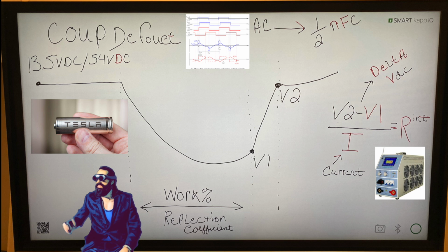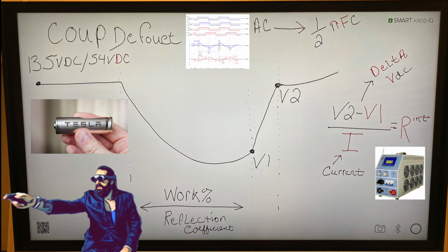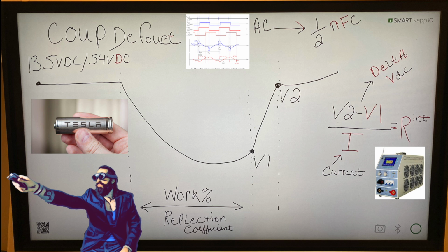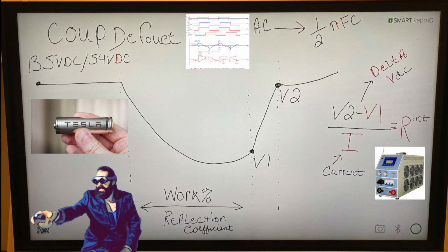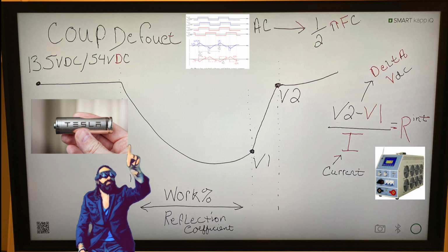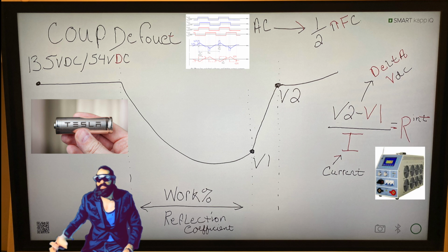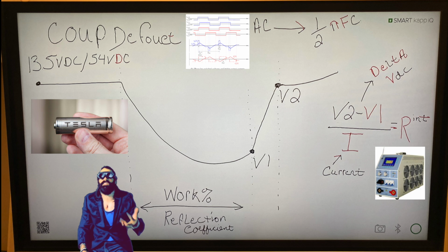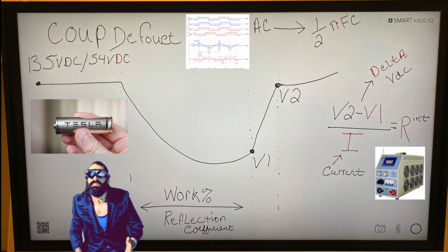And what we generally do is this resistance here that we're inducing from the DC load bank, if we're doing 54 volt load steps, generally in a 540 volt DC bus, you would have 10 load steps at 54, and then this load bank would probably be about 1.6 ohms, right? So if you use Ohm's law, very simple again, you got 54 volts divided by 1.6, what are you getting? You should have about 30 amps. And that's pretty amazing. It's simple stuff that you can look at, you can implement, you can show, you can discuss and review. And again, as you're looking at these systems and battery technologies, if you don't understand how we test them effectively, then you're never going to know when there's a bad battery and it could cause an outage.